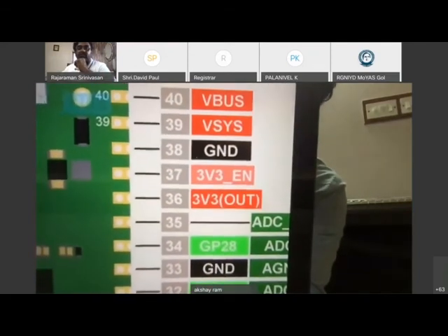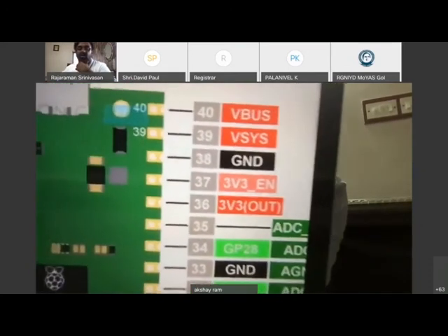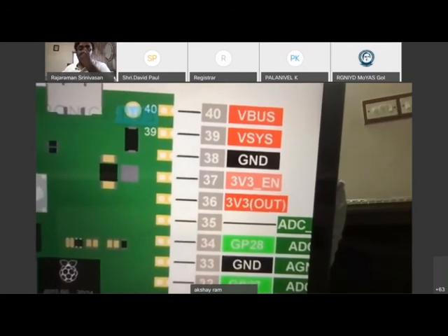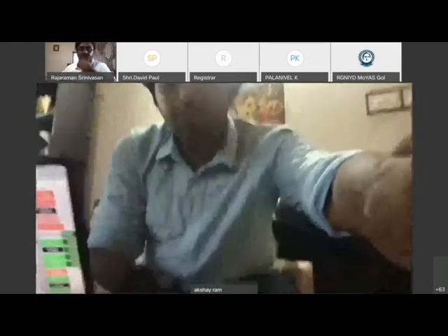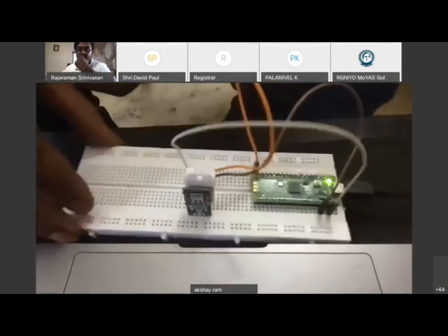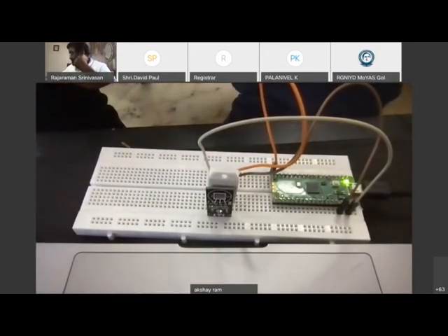So instead of putting it on the ground in the breadboard, you have connected it to the ground in the Pico. Yes, directly connected to Pico because now, say like the example where we were using multiple LEDs, we have to ground all of the LEDs to the Pico.